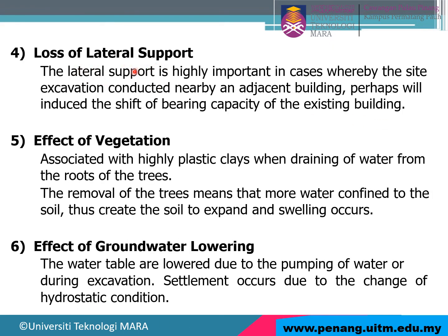Alright, loss of lateral support. Lateral support is highly important in cases where site excavation is conducted nearby at an adjacent building, which will perhaps induce a shift or affect the bearing capacity of the existing building. Meaning that if you have a new excavation conducted nearby an adjacent building, it will affect the old building. Next, the effect of vegetation associated with high plastic clay: the roots of the tree drain water from the soil. The removal of the tree means that more water is confined in the soil. This causes the water to expand and swelling occurs. So this one is for high plastic clay.